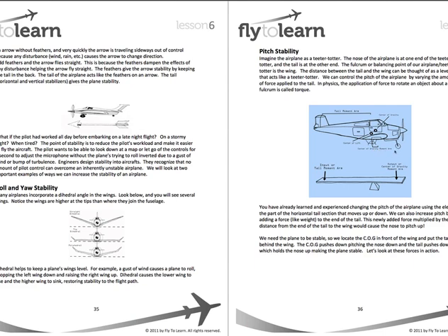Now, what's center of gravity? Center of gravity is, if you can imagine, I can take the airplane and balance it on my finger. That distance between the center of gravity and center of lift is the center of gravity moment arm. And then the tail moment arm, again, is from the center of lift to the tail.